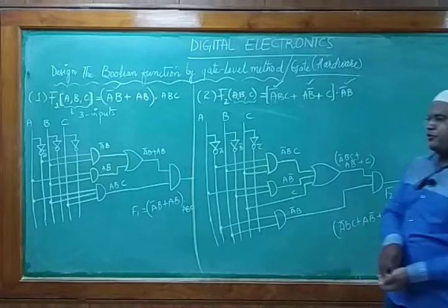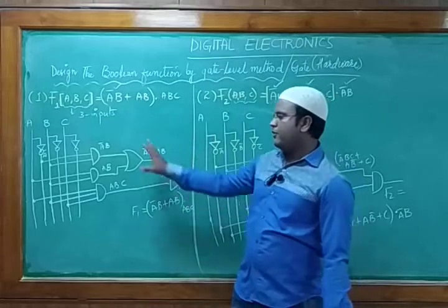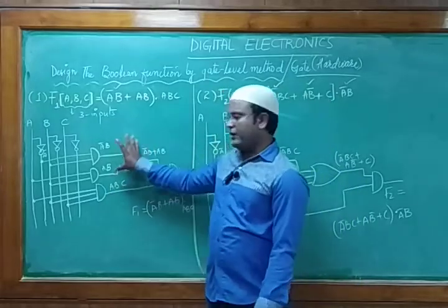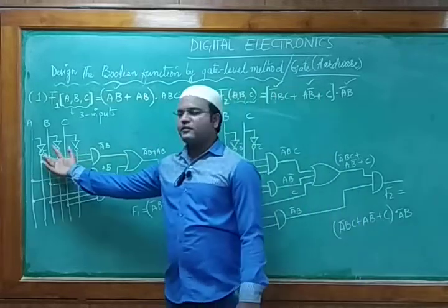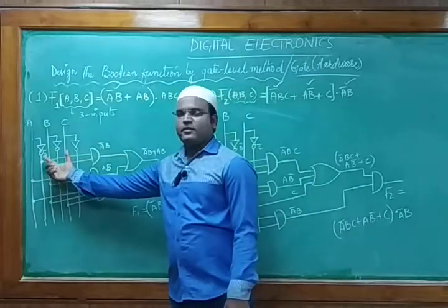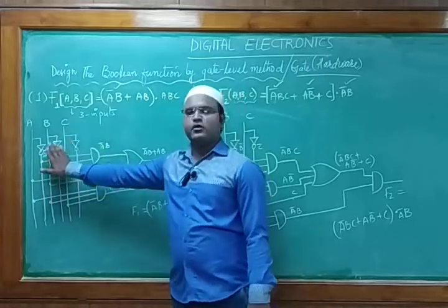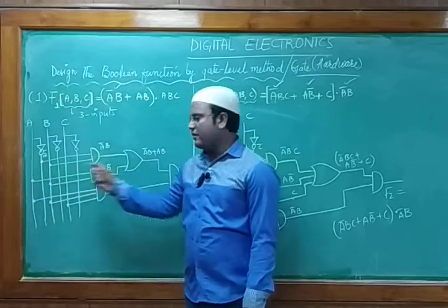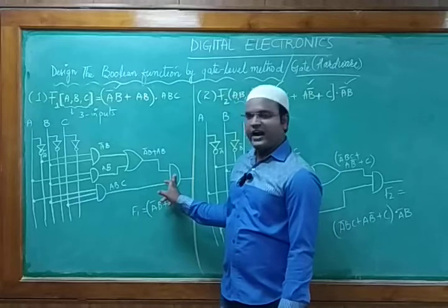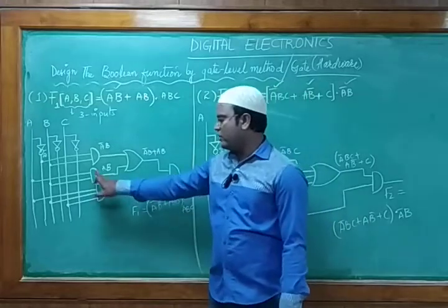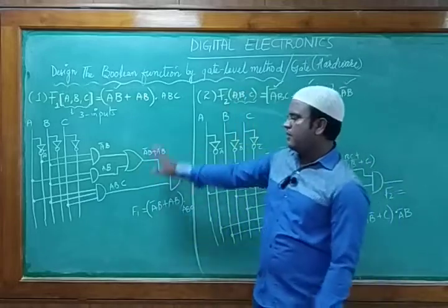As per this, you need to write the analysis. What are you analyzing in the whole thing? We need to write it in statement form. After knowing this designing part, how many gates are required? As per the requirement, we required the procedure for it. We can write one NOT gate is required, 3 AND gates, because here also we are using, 1, 2, 3, 4, so 4 AND gates. Next thing is what? One OR gate.